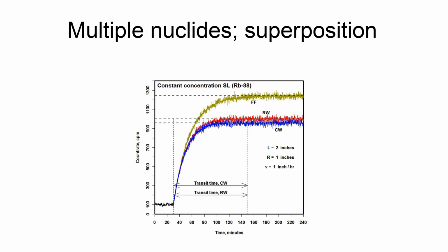However, since the radiation emitted by each nuclide is independent of the others, so that the nuclides present on the filter medium do not interact with each other, the monitor response is the linear combination of the individual responses. Thus, the overall CPAM response to a mixture is just the superposition, i.e., the sum of the individual responses.